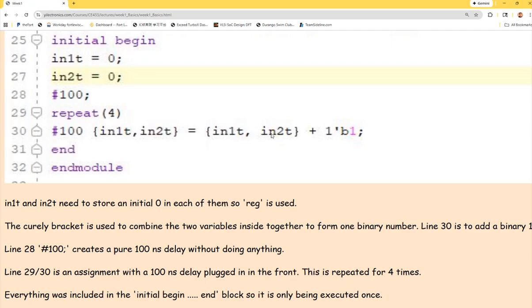So the time delay extends the previous result. And at the end of the time delay, there's just one update. If there's a change, it's going to change. If there's no change, it's going to keep at the point with the same value. So that's going to be a dot. This assignment will be a dot at the end of the 100 nanosecond time delay. So when you plot it, make sure that you have the extension and then update it as a dot.